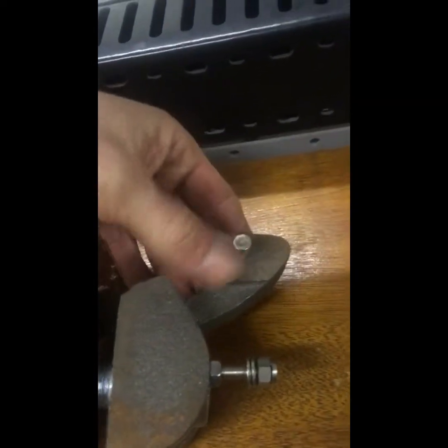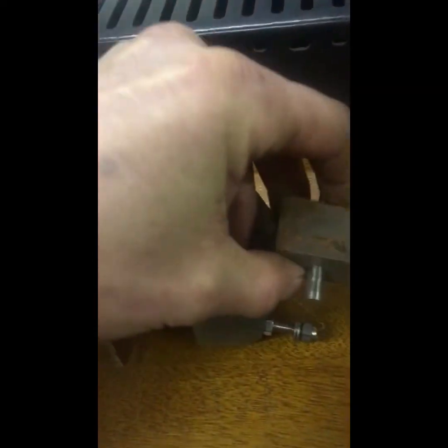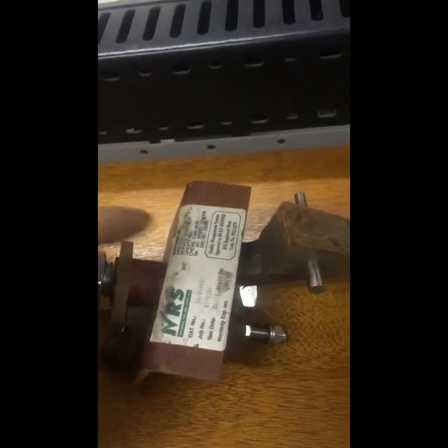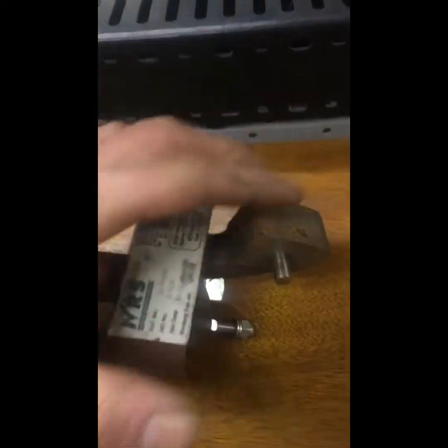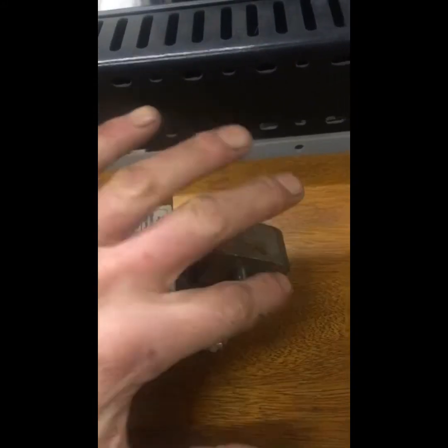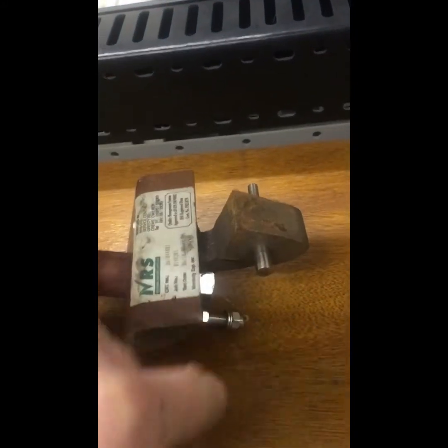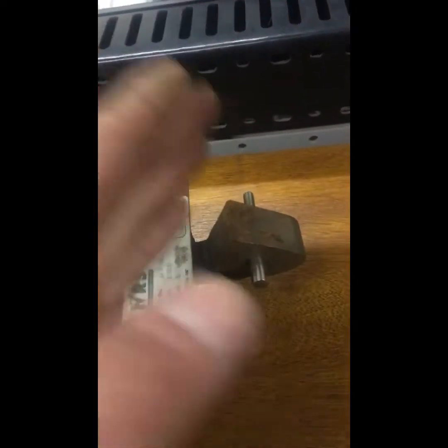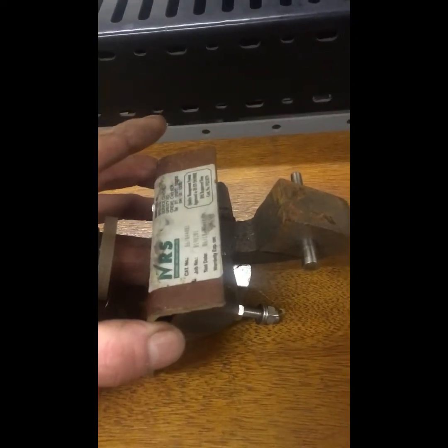There are older versions of these which don't actually have plate insulation as well. Those tend to be through the rail, direct and out. Not the greatest idea, because what you want is when this shears off, you don't want this to accidentally fall back onto the web of the rail and still keep the circuit up. You want it to shear off and break the circuit, hence the insulation here.